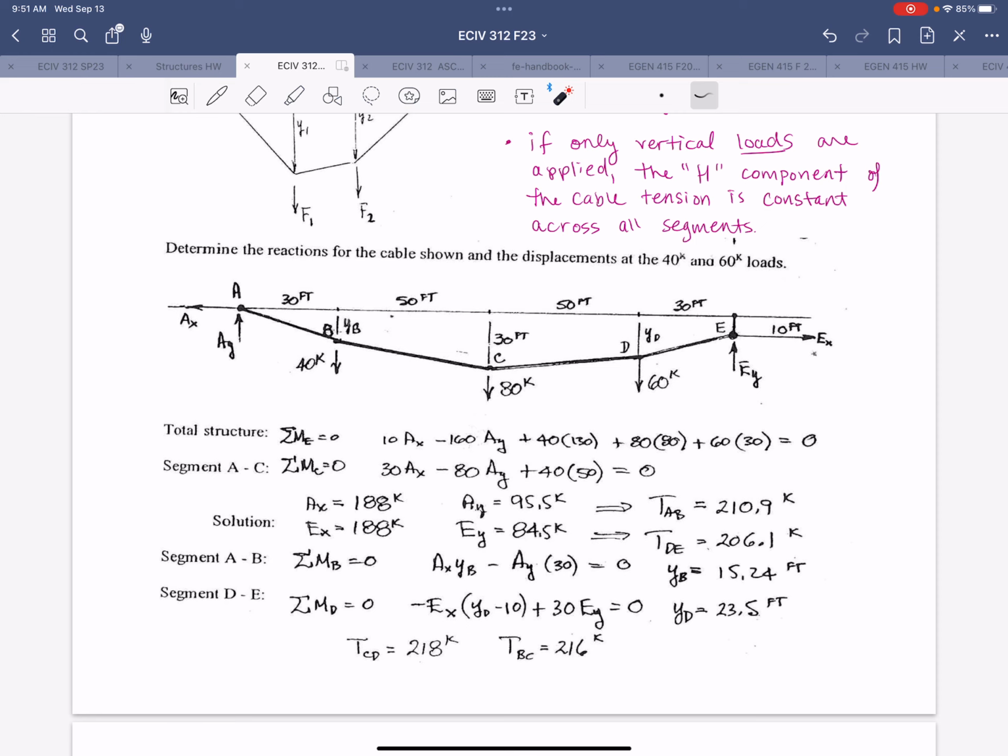Questions? Yeah? Why do you think the ties are all in one direction? They don't put the ties in the other direction too? Oh, okay. Yeah, great question. So they don't expect these ties to ever be in compression, so that indicates that they don't expect the load to ever reverse, right? So it's just always going to be a gravity load. They probably don't anticipate many other load cases. So that's probably the reason.